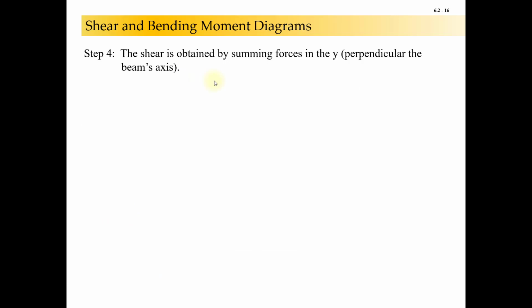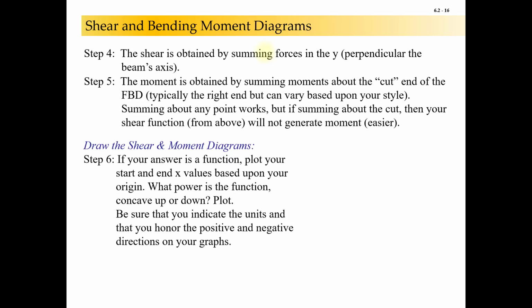We are going to determine our shear and moment functions by, for shear, summing forces in the y, which is the axis perpendicular to the beam's axis. So we're just doing a beam. And then for moment, we're going to sum moments about the cut, so that we don't have functions times distances. We have reaction values times distances. It makes our math a lot easier.